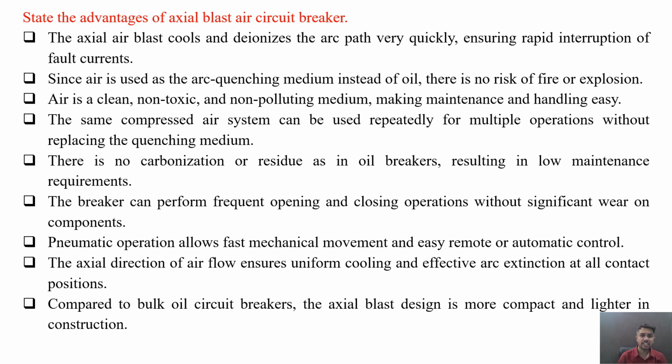The same compressed air system can be used repeatedly for multiple operations without replacing the quenching medium. There is no carbonization or residue as in oil circuit breakers, resulting in low maintenance requirements. The breaker can perform frequent opening and closing operations without significant wear on the components. Pneumatic operation allows fast mechanical movement and easy remote or automatic control.